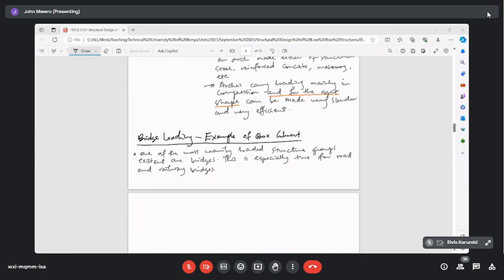One, you're putting in a lot of imposed load, courtesy of the merchandise. Secondly, you're attracting more people onto the bridge, so the human loading that you allowed for becomes exceeded.